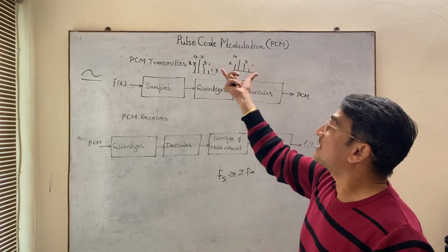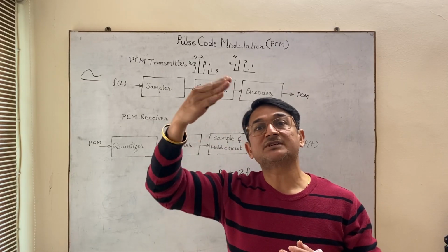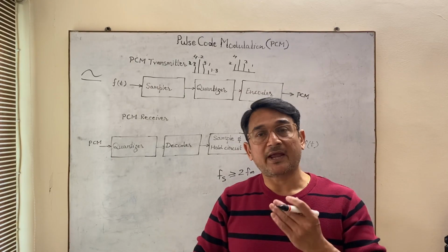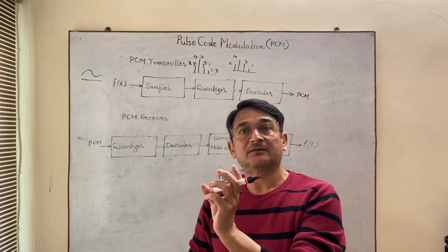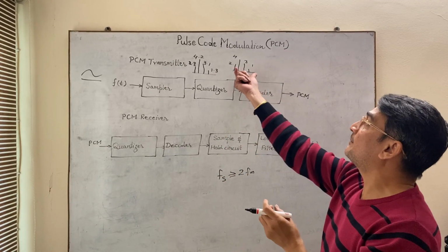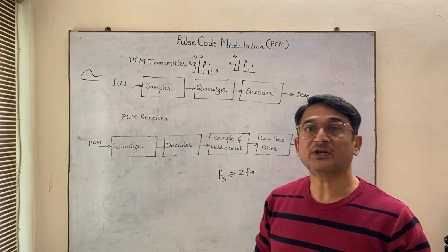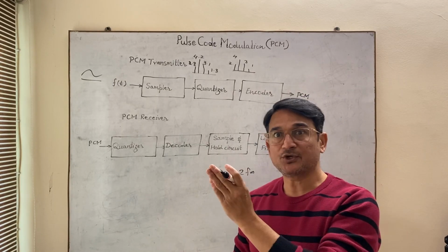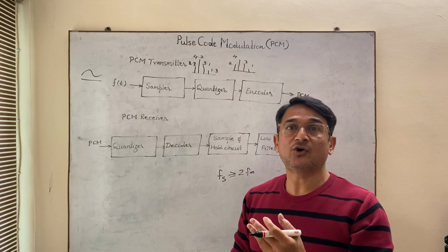Now the encoder circuit will check all the samples and find the largest sample. That largest sample can be converted into binary bits, and the length of the binary bits will be decided by the maximum sample. In this case, the maximum value of the sample is 4. It can be converted into binary as 100, because the other samples are below the value of 4.